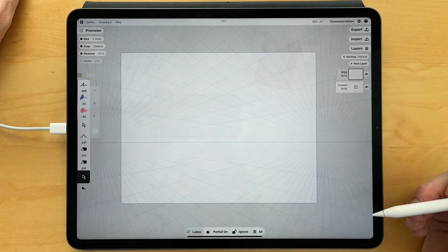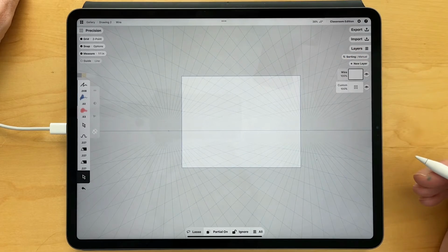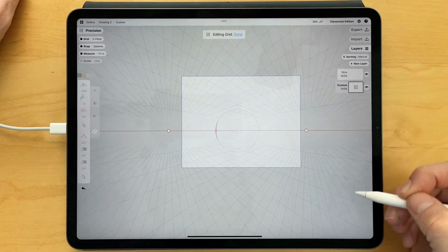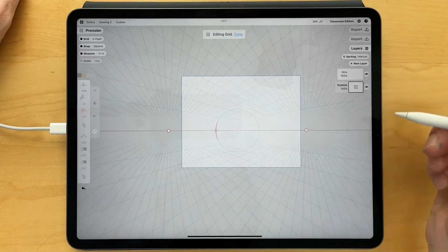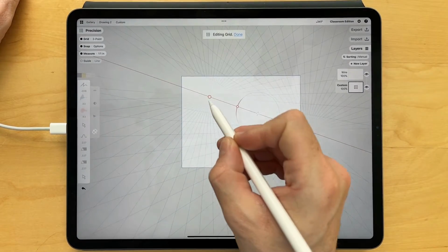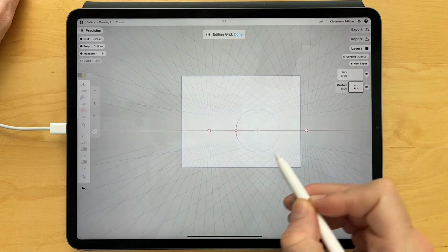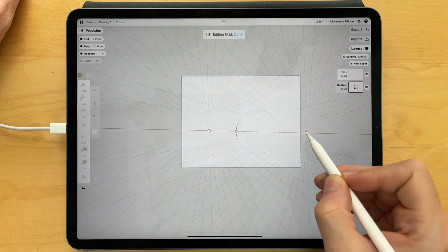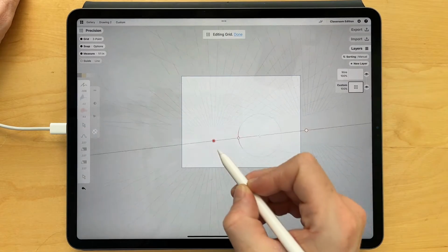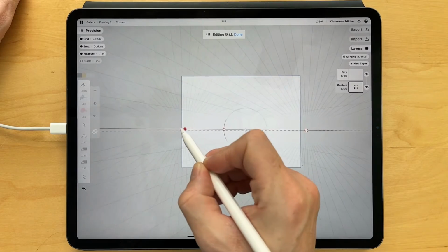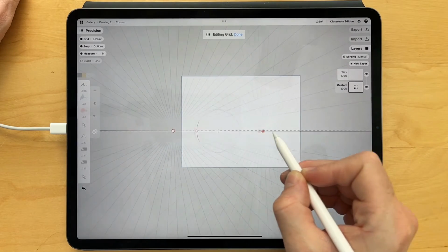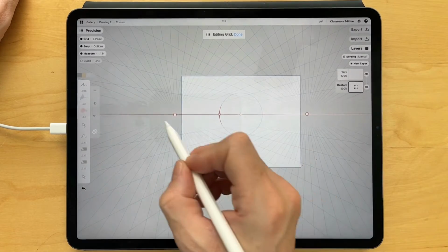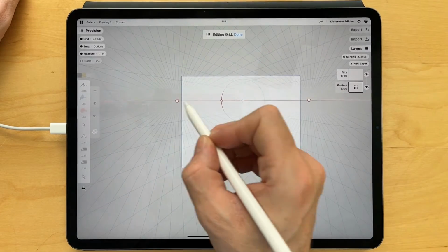Sweet. Okay, so how do we configure that grid when I zoom out? We can tap on this. That actually activates the grid layer, aka the grid. And now I can move this around. So I'm rotating it and you see there's a dash line and the software snaps to it. If I wait, then you see it goes away. So this is a very easy way to make the grid always horizontal or vertical. This is the left and this is the right vanishing point. By simply adjusting those, also going up and down, I specify where the horizon line is and where my vanishing points are.